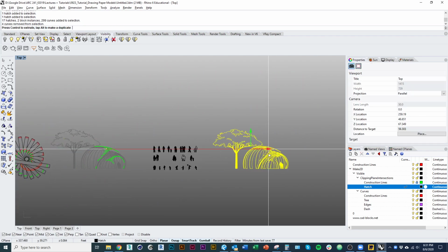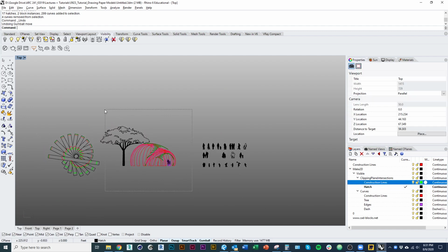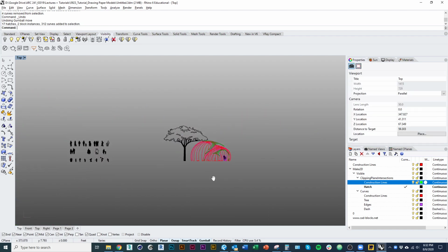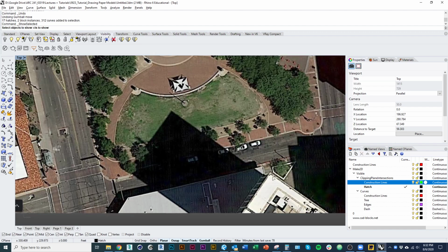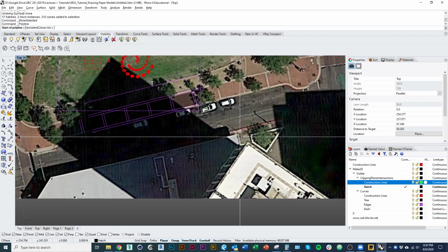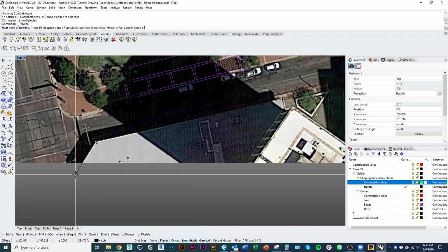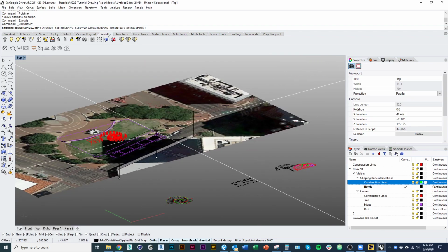Maybe you make a model of, I didn't layer lock here. Maybe you make a model of the volume of the building. We could model just a quick mass. For example, we could just quickly trace the outline of this building and extrude it, just to get a quick reference for how tall it is right there, 24 feet.